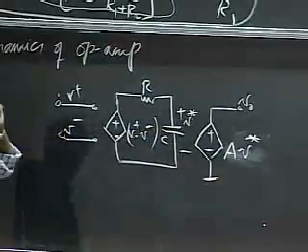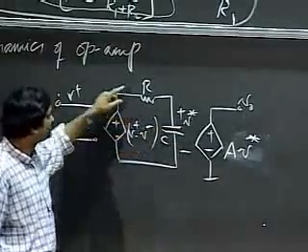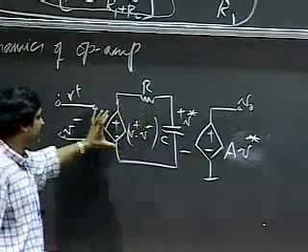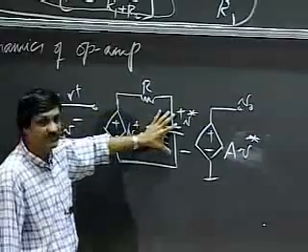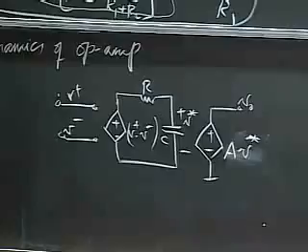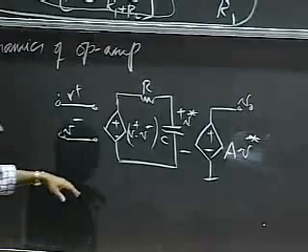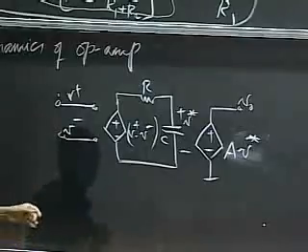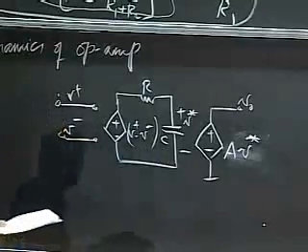Okay, notice that if it turned out that the resistance here, for example, was 0, then V plus minus V minus would appear across V star, and this would be A times V plus minus V minus, what you've seen before. Okay, it's always good to take a look at circuits and look at what happens when some component goes to an extreme value. This would give you a basic op-amp circuit.